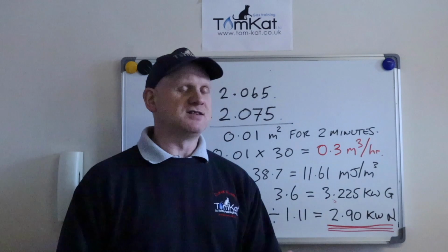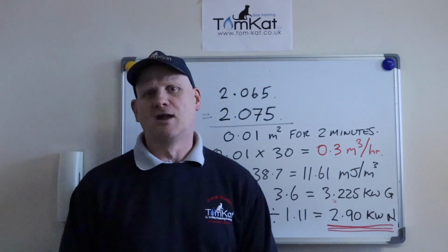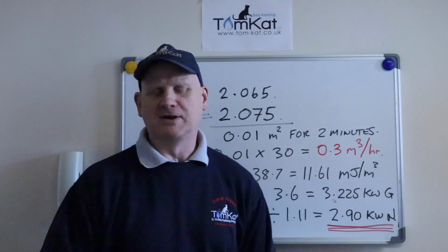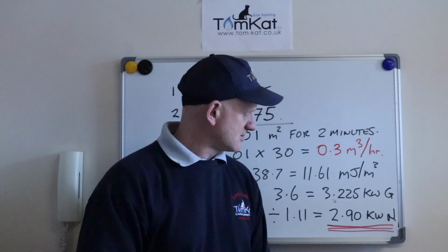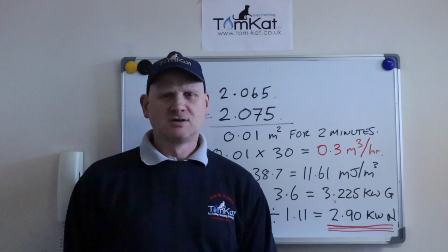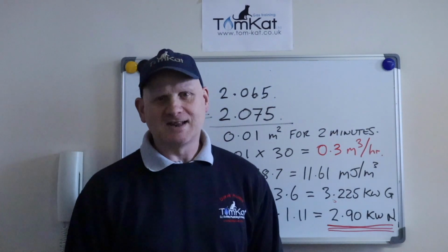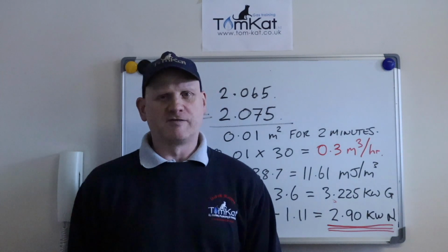So once you've taken this reading, the manufacturer's instruction says 2.9 kilowatts. I think that's why I picked that ring. Anyway, but if it had said 3 kilowatts, would you have allowed it? Well, I certainly would. Okay, and I'm sure 99.99% of the gas engineers would pass it off that gas rate.